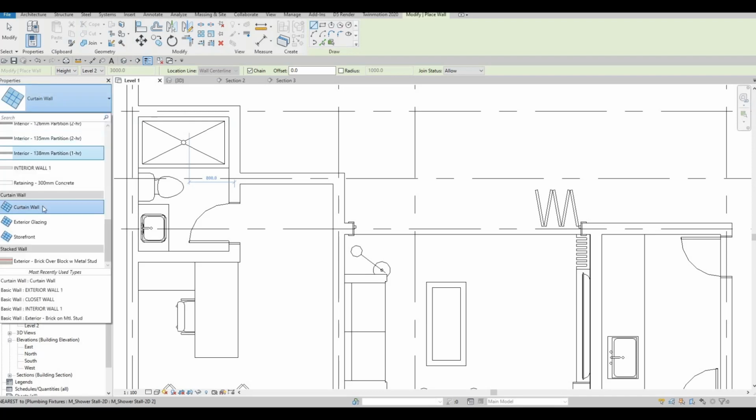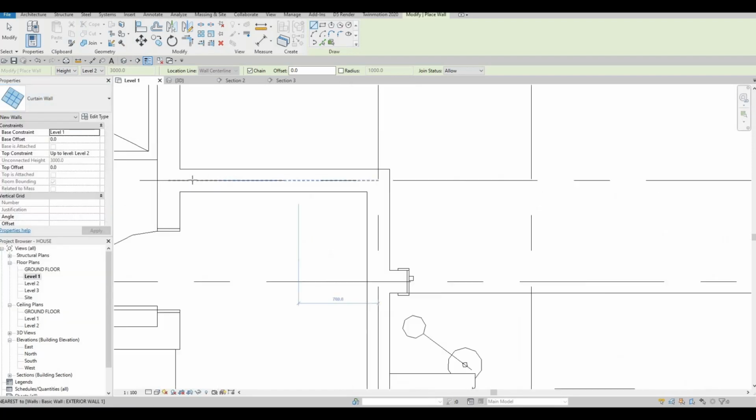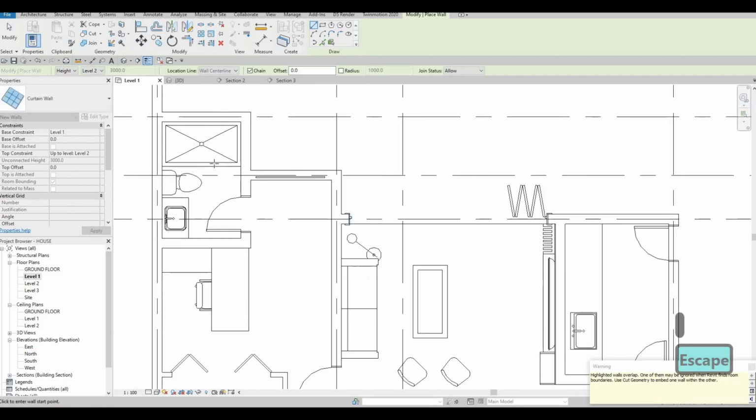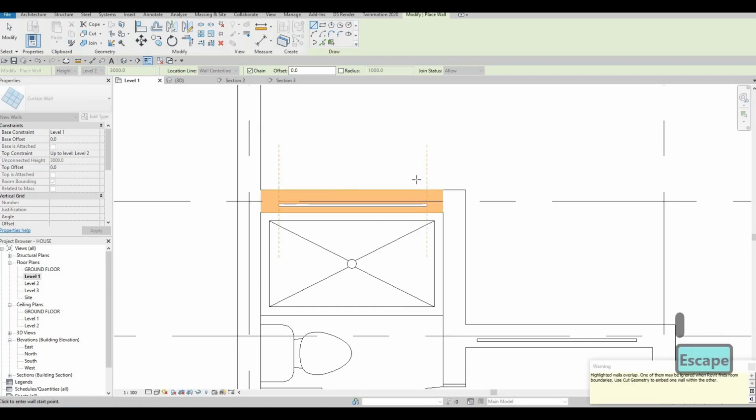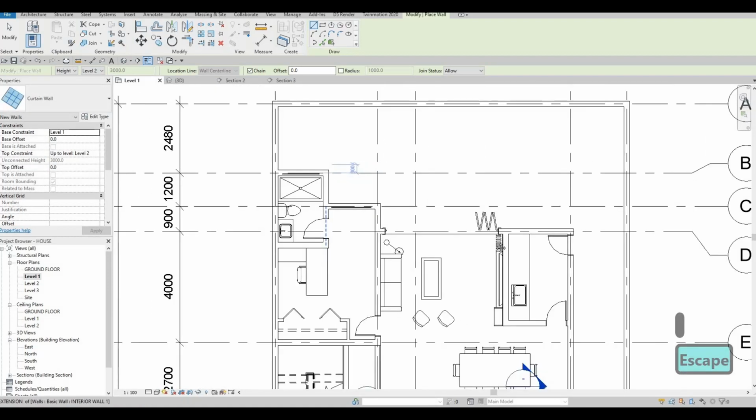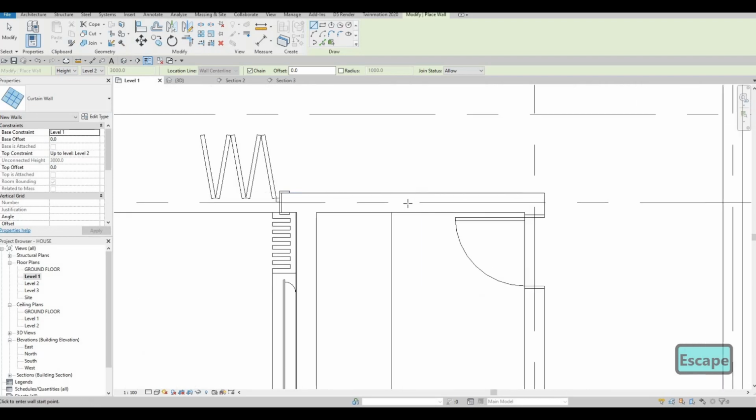We just need to drop down, and basically it's right here, and we need to add it from here, but you need to click on spacebar so that it's from the inside. So don't worry about that. That is just Revit saying that it's not visible at the moment yet, so that's fine.